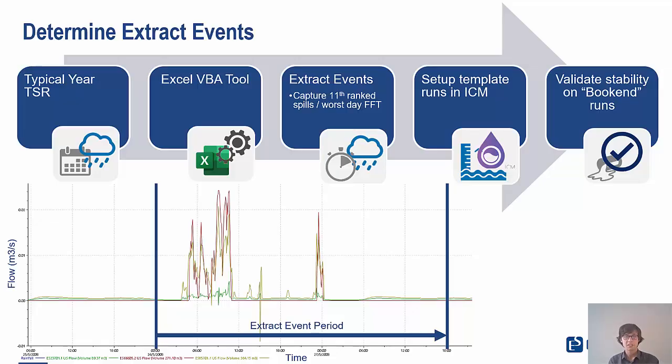Now, with the time periods established, we'll set up the template runs for the optimization to then edit. These will include usually initial state hot start files to capture the antecedent conditions, which has so far in most cases proved accurate enough despite widespread upgrades being applied across the network.